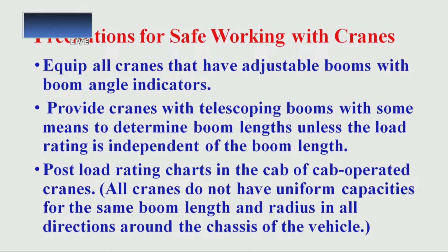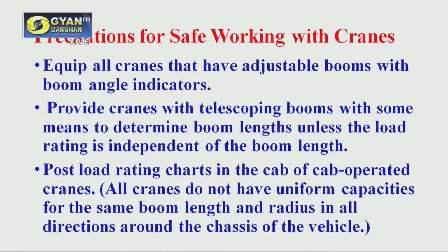First of all, equip all cranes that have adjustable booms with boom angle indicators. Second, provide the cranes with telescopic booms with some means to determine boom lengths, unless the load rating is independent of the boom length.